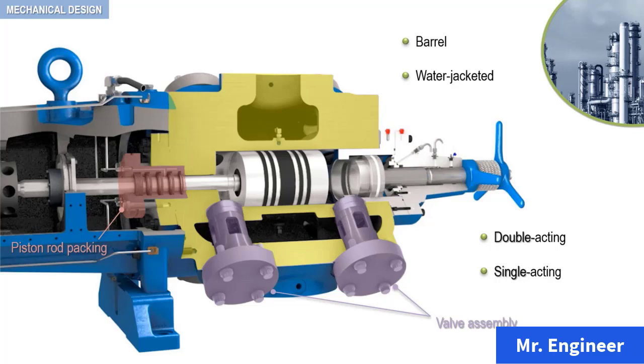Keep in mind, all cylinders can be modified to provide capacity control, or to provide openings for clearance pockets and internal plug and loaders. This will be discussed in detail in the capacity control section.